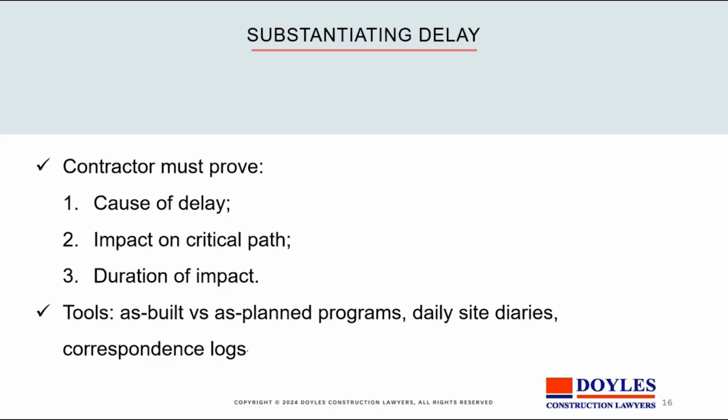Usually, again, substantiating delay is important, and you've got to take it as a contractor that what's obvious when you look at site today might not be obvious when the delay claim is assessed in perhaps a week or 2 weeks or 4 weeks' time. So you've got to look at proving, in lots of cases, proving the obvious. If you take a picture today of the flooded trench, then provided your metadata of time, date and location is pretty good, that should be accepted.